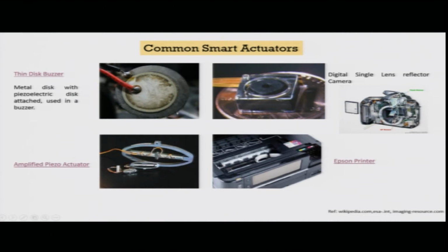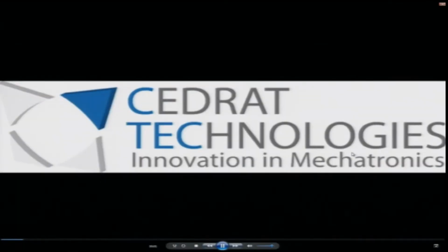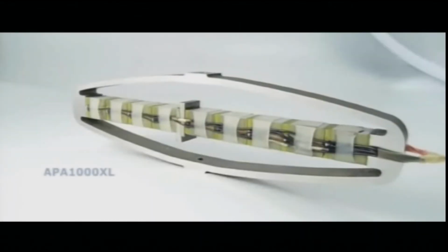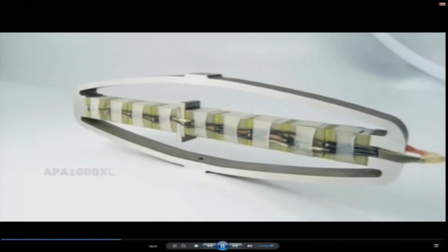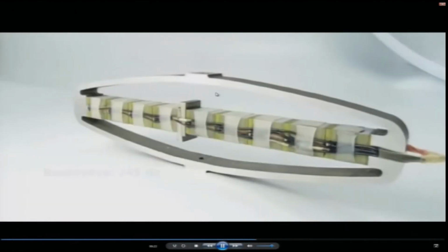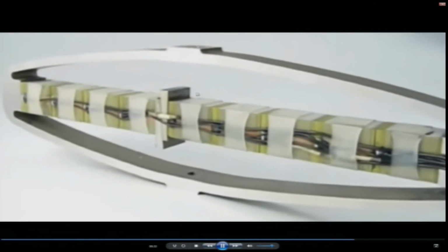Somewhat more, you can actually increase the effect of it if you look at the amplified piezo actuator. In this particular case you see how you can increase the effect, how you can amplify the small amount of deformation that you get from a piezoelectric material. As you can see, there is this core here which is a piezoelectric stack. There are n number of these piezoelectric materials in the core, and it is connected to this oval shape, and this is where the output is. The resonance in this case is at 245 hertz, so you can vary it and design it accordingly.